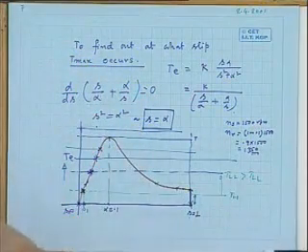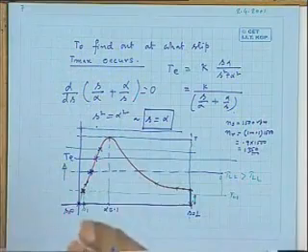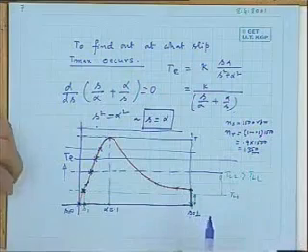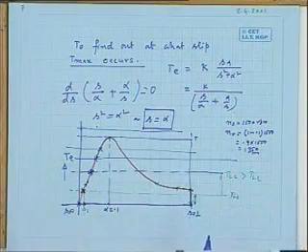Machine will go on decelerating because TL is always greater than electromagnetic torque. Machine will go on decelerating and finally come to S equal to 1. Are you getting? So therefore you find in an induction motor, as you go on increasing the load torque on the shaft of the machine, machine may come to a stop if the load torque demand exceeds the maximum torque the induction motor can develop. Are you getting? Therefore, induction motor will operate only in this zone.